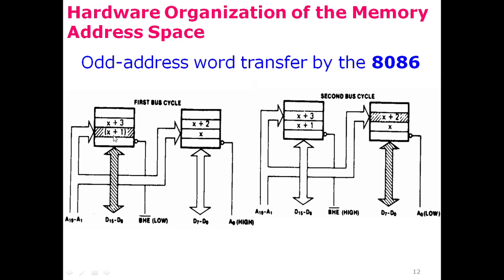Only the byte selected in the odd bank is read through the D8 till D15 data bus lines, and this is provided low, so this high bank or odd bank is active in this bus cycle, while this bank is kept non-active. This is provided 0 is high, so this is not selected. So the byte is only transferred from this high bank.